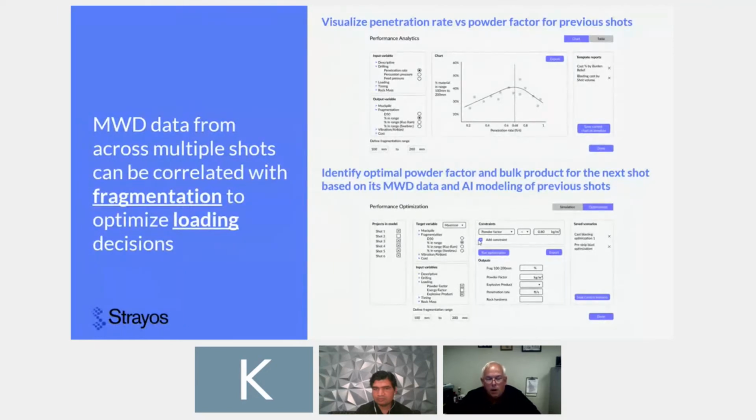And it's not always just penetration rate. It could be in rotation pressure, your feed pressure, or even your flushing pressures. You can see differences in there, which tell you that changes are happening in your geology. And as you get predictive, it tells you this is what I need to do differently to help you get a better picture on how to optimize. And as I said, this is not subjective anymore. This is now quantifiable data that you can go back on and measure.